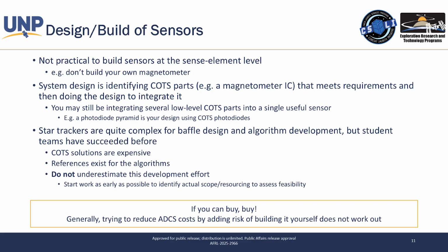So if you think about this, and I want everyone to do this experiment right now, so you're all going to look silly together. If I can get one measurement and I know where the sun is, that's essentially a vector in space. So if you stick your arm out and let's pretend you're pointing at the sun, great, I know where that is. The problem is you can roll about that vector. So I still have 360 degrees of ambiguity in where I'm pointing.